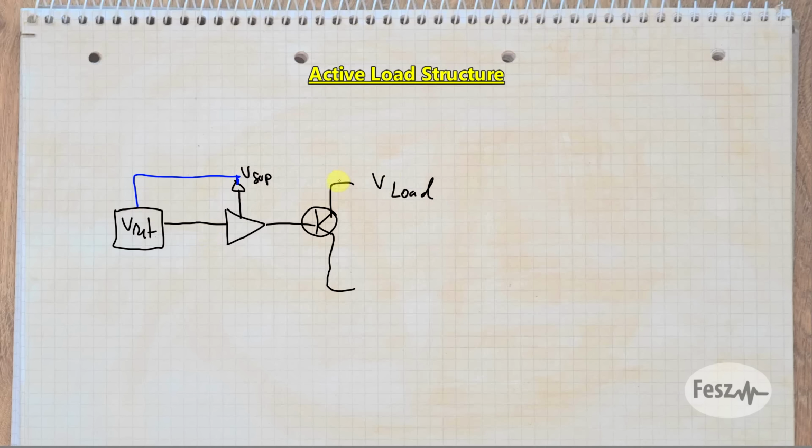The second important simplification that can be done has to do with knowing the load voltage. As long as this is always above a few volts, you can simply take a small LDO and power the circuit from the load itself. So in the final build, this is the way I chose to supply the board. Now, taking this approach does bring a few limitations. I mean, you want the circuit to work at lowest possible load voltages.